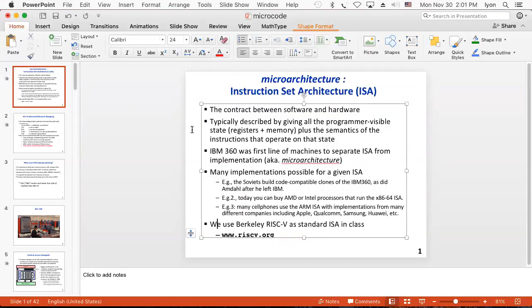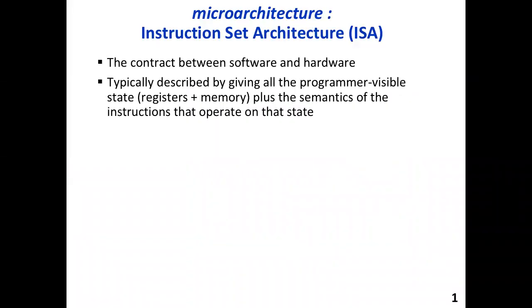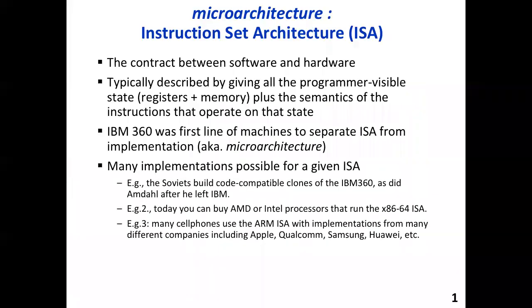In fact, the way to do this is to execute a program that's stored in the hardware, and it is called the microcode of the machine. You can actually code a CPU in microcode, and it gives you a very symmetric sort of instruction set. So when you go to create new instruction set architectures, you can create new microcode programs that will give you new architectures.